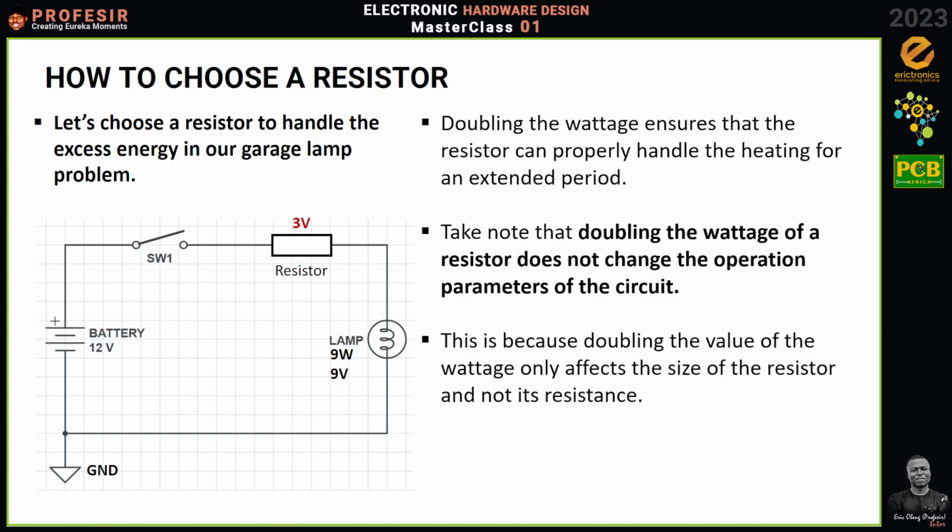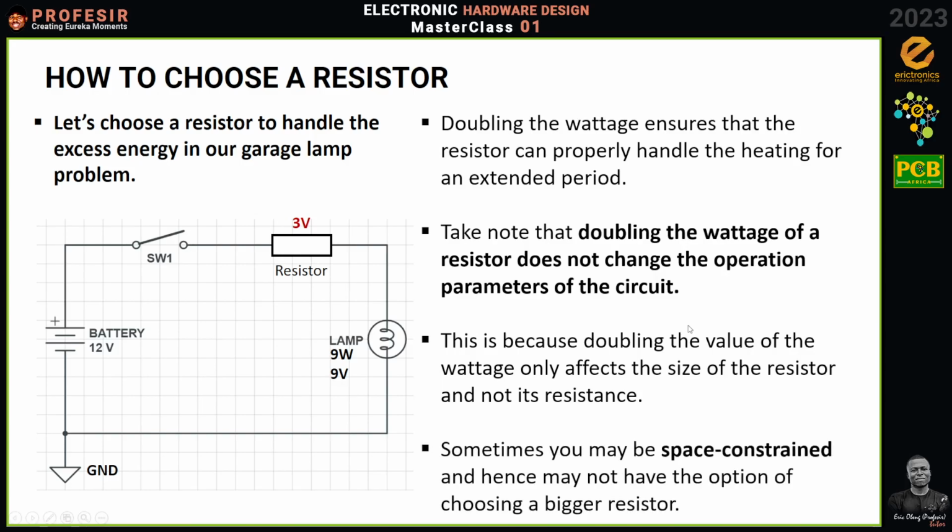Now take note that this is not the same as other components or devices in circuits, okay? The wattage of a resistor is related to the amount of heat it can dissipate, or the amount of energy it can dissipate, not the amount of current it can consume. Exactly. So understand the difference. Increasing the wattage only affects the size.